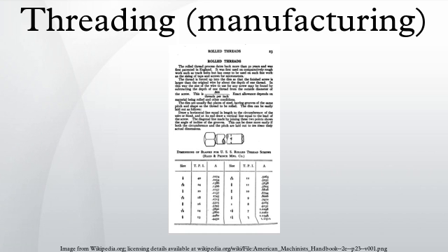Thread lapping: rarely, thread cutting or grinding will be followed by thread lapping in order to achieve the highest precision and surface finish achievable. This is a tool-room practice when the highest precision is required, rarely employed except for the lead screws or ball screws of high-end machine tools.